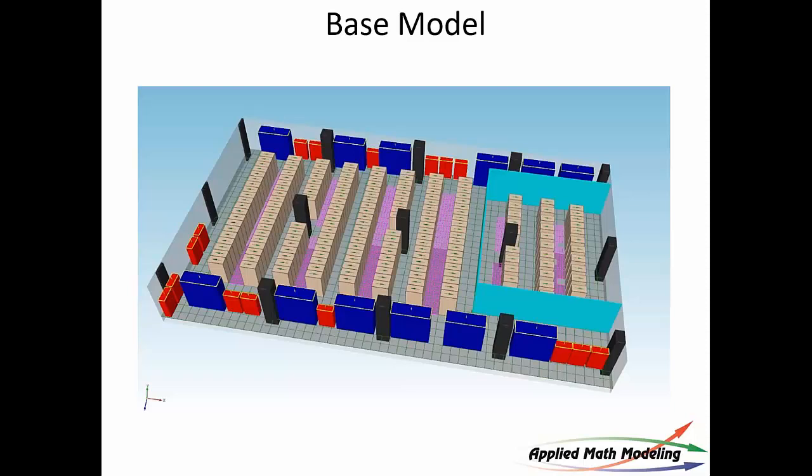It's nothing very complicated. This is what we call a naturally convective return data center. You see on the perimeter these cooling units. These are air handlers, these are fan coils, downflow in this case, raised floor data center, with perforated tiles in front of the servers. It's lined up perfectly in terms of hot aisle, cold aisle. The hot aisles are here.